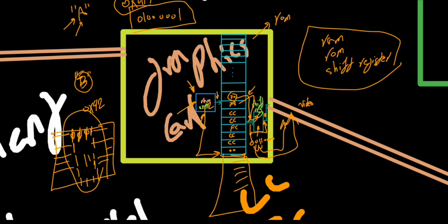So in our imaginary graphics card, we need a RAM capable of 1 byte of data, or 1 memory cell. But our RAM has to be much bigger. It depends on how many characters we want to show on the display. If it is all the uppercase letters of the English alphabet, which are 26, then each character needs 8 bytes to be represented by, which are these 8 bytes in here. Therefore, we say 26 by 8 is the minimum capacity of RAM that we need. We also need 1 shift register.